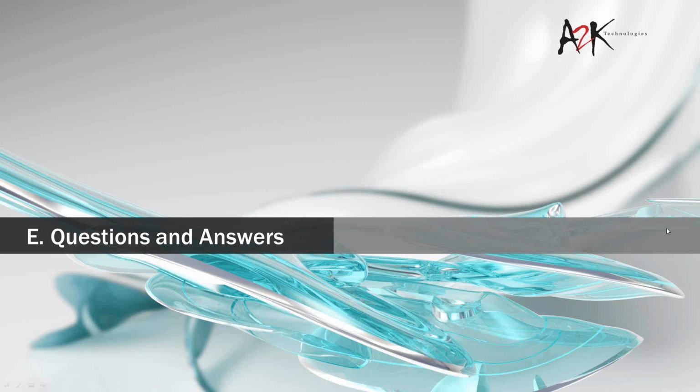Next question on there is, how important is it to use the Vault within the application to keep association and links between files? So in terms of CAD data, like Inventor, for example, we have lots and lots of links. When you've got lots of links between the CAD data, then it's very important to use the CAD application to check it in. Because if someone just drags and drops, say, an assembly file into Vault using just the Windows folder structure, then it'll just bring the assembly file. It won't bring the children, and it'll lose those links. So when using CAD data with links, it's very important to use the CAD application.